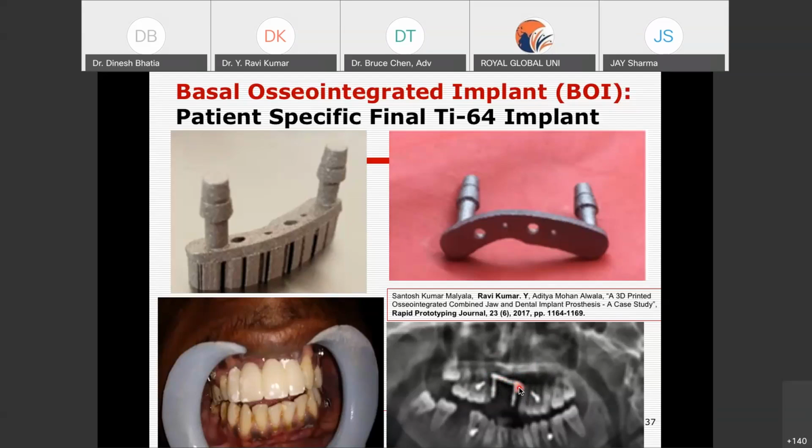So which you can see, there is a permanent implant. This is fabricated again from the powder bed system. Titanium 64 is the material used, and this is with supports. After removing the supports, post-processing and sterilizing, it got implanted here, and this is the positioning